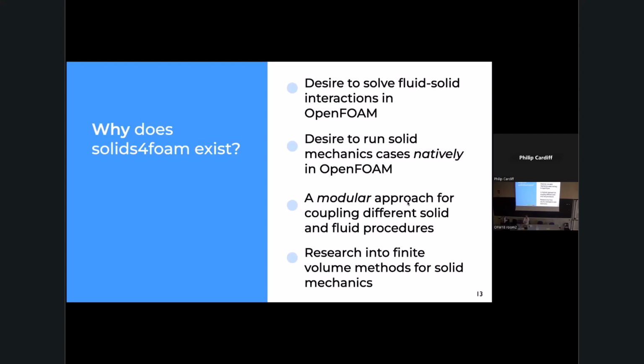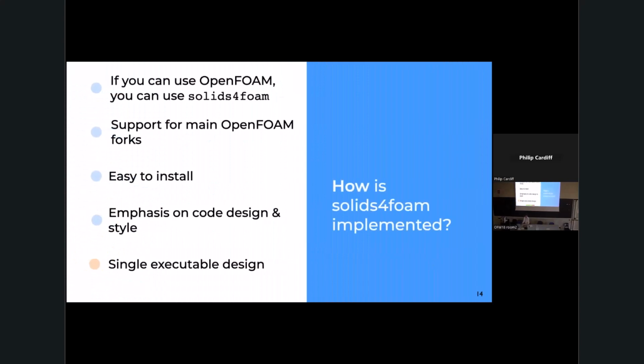Originally, when you wanted to do FSI in the OpenFOAM-style approach, if you wanted one type of fluid solver like pimpleFoam and another type of solid solver, you had to copy and paste them into the same solver. So if you wanted to change something, you had to make a new solver. Having a modular fluid and a modular solid means that at runtime, you can select which ones you want to use. I'll talk a little bit about that. And one thing for me as well, I'm interested in finite volume methods, particularly for solid mechanics and FSI, and exploring new numerical methods. So it's essentially a toolbox that lets me and others do that.